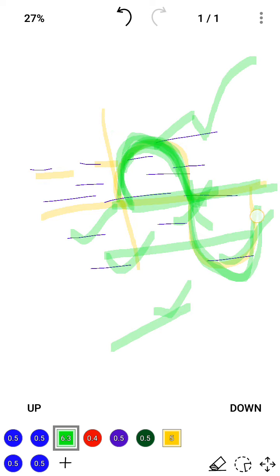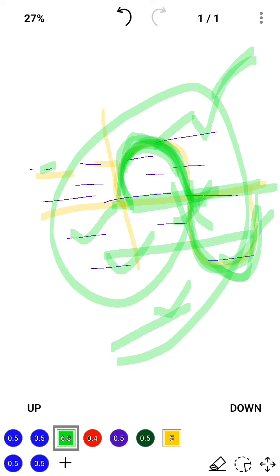Velocity modulation means a change of velocity. The electrons traveling in the positive half cycle get accelerated, and the electrons traveling in the negative half cycle get decelerated. Finally the change in velocity appears, so this process is called velocity modulation.